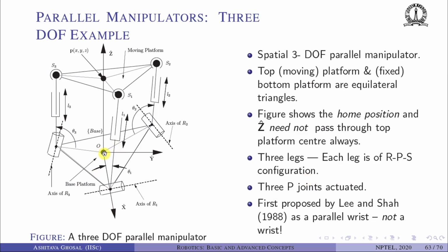we can have a transformation matrix between this base coordinate system, which is x, y, z, and this origin, and the L1 coordinate system, which is here. So in this figure, we can see that the translation from the base origin to the origin is along the x-axis. Okay, whereas for this, it is not along the x-axis, it is at some angle to the x-axis.